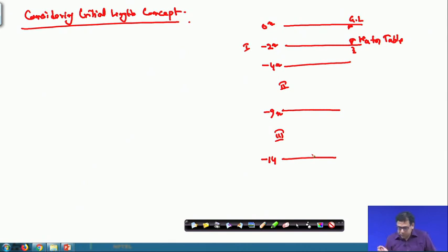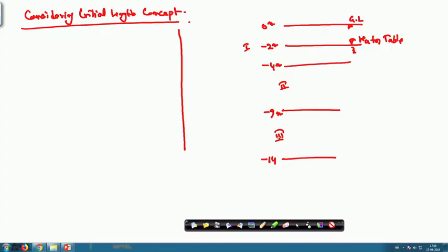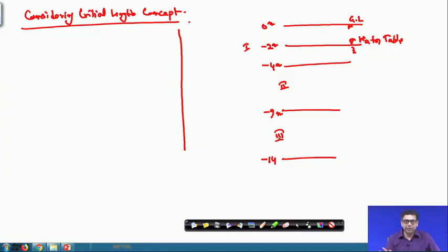So, the distribution will be, now if I draw the stress distribution. Now the question is which critical length we will consider, because this first layer is the loose sand, second layer is the medium sand, third layer is the dense sand. So I would prefer to take the critical length divided by d as 15, because that is the range from loose to medium, and for the dense sand it is 20, but the top portion is loose to medium.